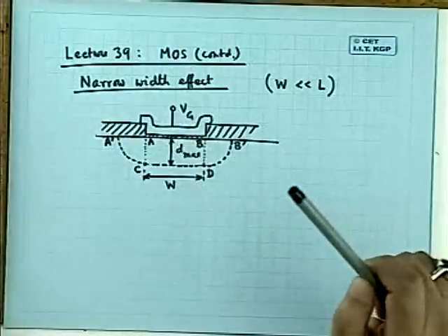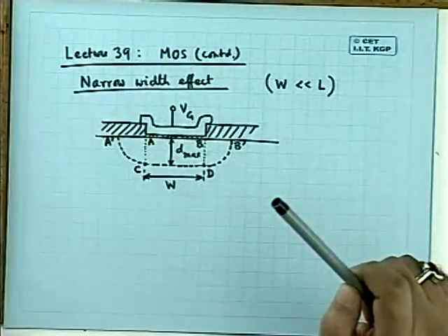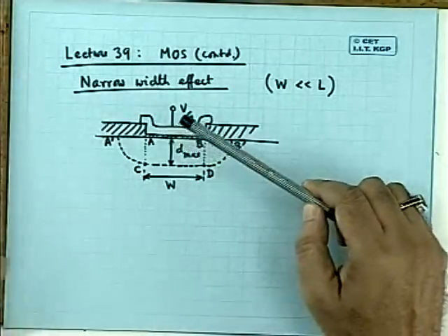You have to do something to remove that inversion layer. What is to be done? Exactly the same thing which you did here to control the threshold voltage. Here you just adjusted this surface implant such that the threshold voltage was the desired value of 1 volt. But in the remaining region, I have to make a situation where the inversion layer is thoroughly removed. There is a threshold voltage called field threshold.